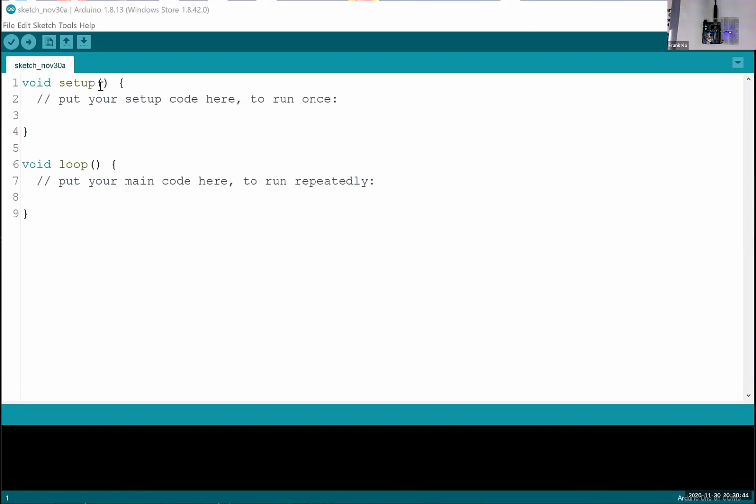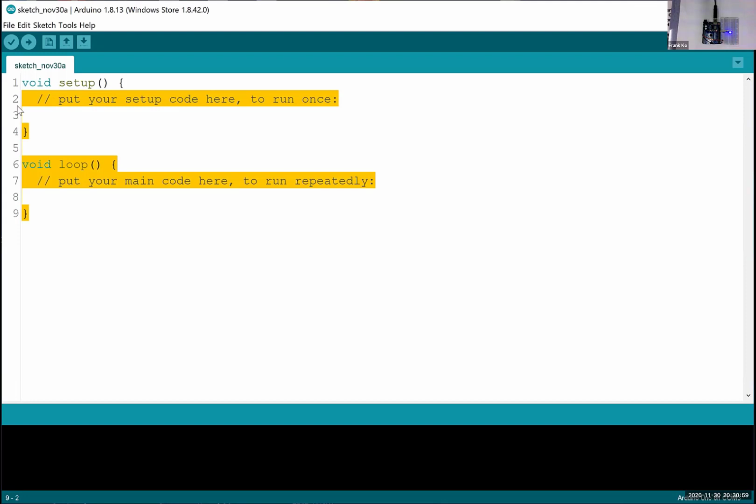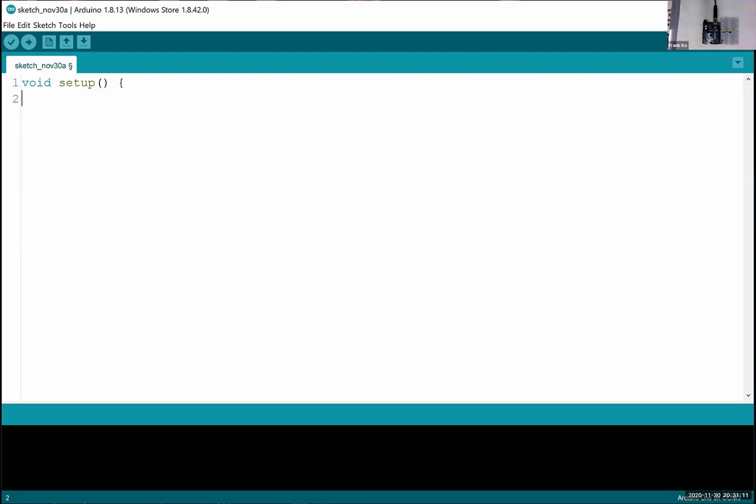Okay, so I'm going to skip all the comments. The very first thing is void setup, open parentheses, yes? And then the next chunk of programming will be pin mode. So I'm going to take all of this and where's my keyboard? Now I need my keyboard. Let's raise this back up. Delete. Okay, so my next will be pin mode, P-I-N, capital M-O-D-E, open parentheses,